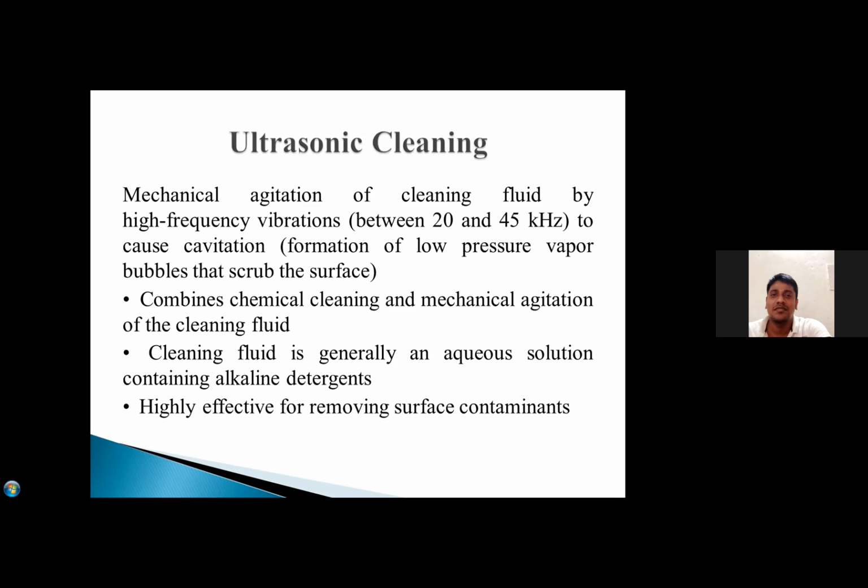Ultrasonic cleaning. This is a highly effective cleaning method. Mechanical agitation of the cleaning fluid by high frequency vibration between 20 to 45 kHz causes cavitation, the formation of low pressure vapor bubbles that scrub the surface. It combines chemical cleaning and mechanical agitation of the cleaning fluid. The cleaning fluid is generally an aqueous solution containing alkaline detergents, highly effective for removing surface contaminants.